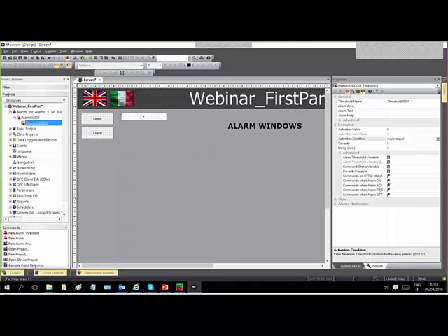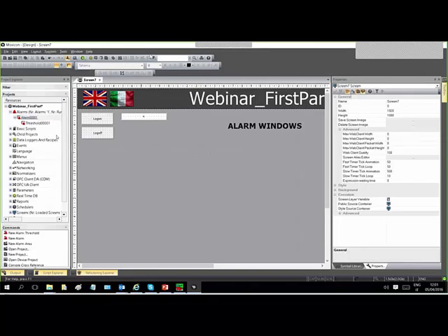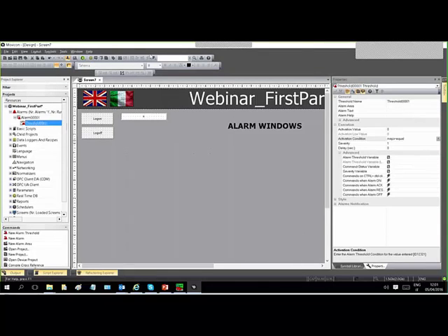Let's do some examples of a digital alarm. There is also a tool, an alarm generator, that lets you generate a lot of alarms with a suffix. Now, manually, our alarm. The threshold properties: you have a threshold name, so you can give a correct name here. I don't know, it could be HHLL, as in the example I just gave you before.